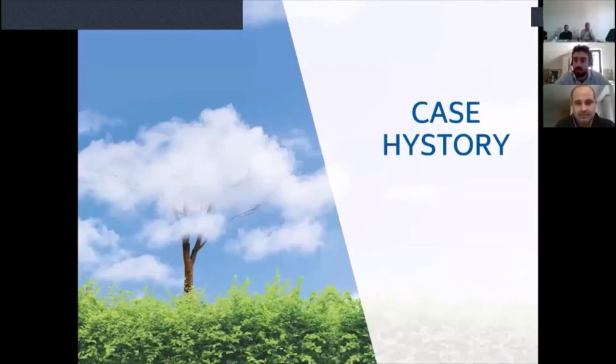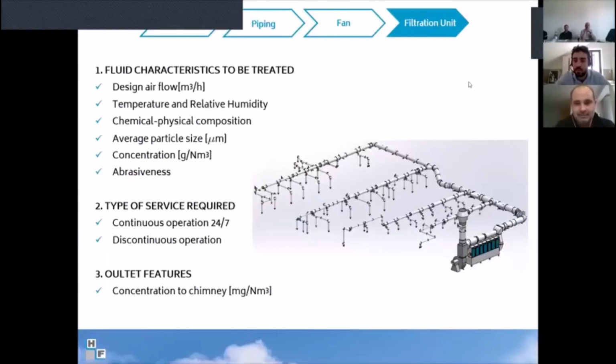Yes. What size was the filter? Going back to the page before. Sorry, Gunther, I don't understand you. It was the MCOS. Okay, this is an MCOS with 7 modules. So it's made for 28,000 cubic meters per hour. It is a double stage filter. I don't know if you know it, but it's a double stage filter.